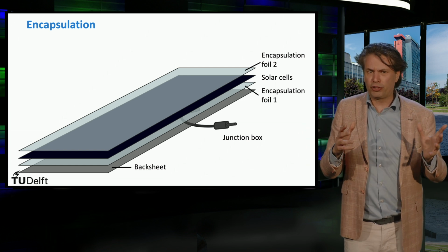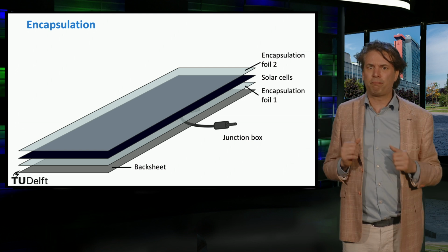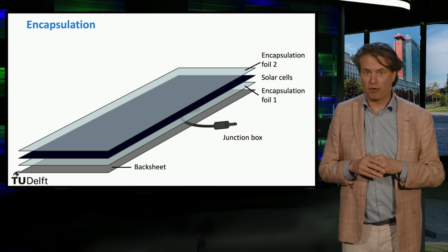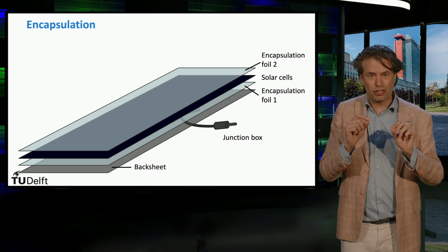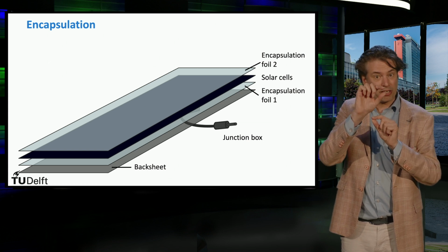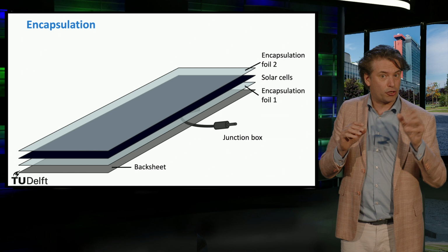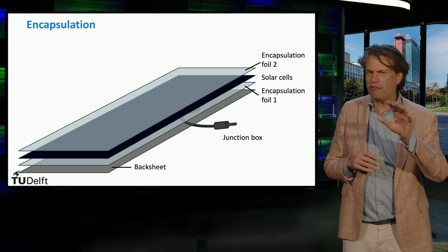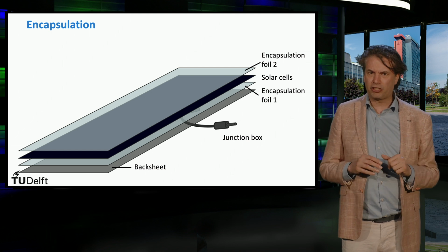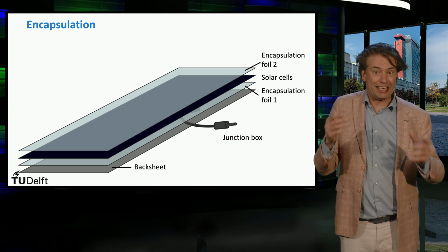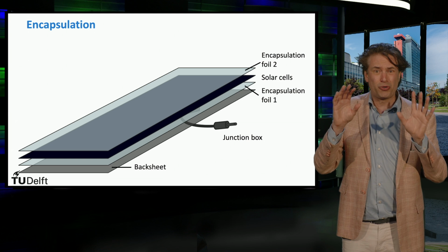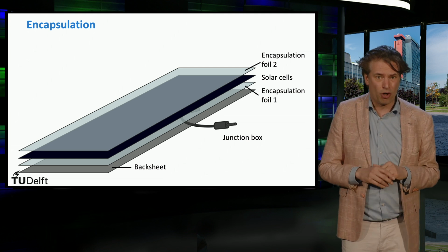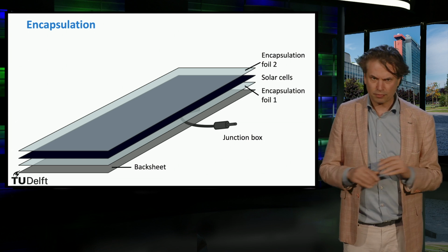For thin film modules, the encapsulation is an important part of the module price. That is because these technologies use a transparent conductive oxide, or TCO, as a front contact. TCOs are generally very vulnerable to degradation by water vapor, which means that the encapsulant must be really good in order to enhance the lifespan of the module.